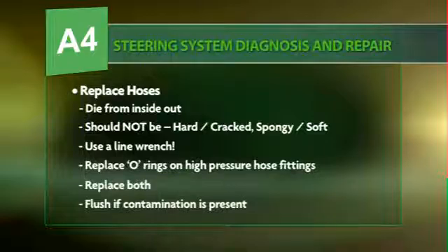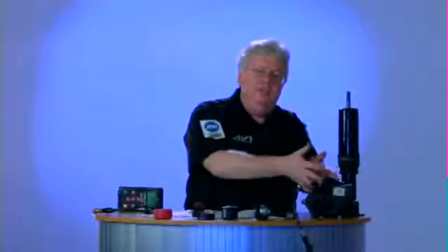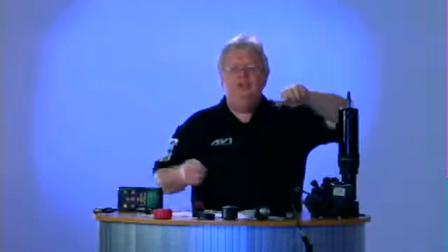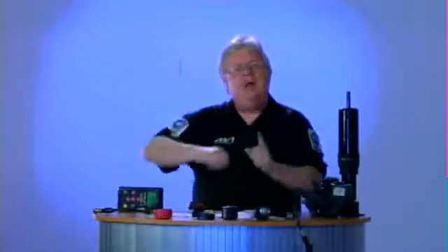So you want to take the return line loose out of the pump, and you want to fill the system as the engine runs, and you turn the steering wheel from lock to lock, but don't hang out, don't prolong the lock where you're hearing the pump groaning and laboring. Just do it for a second and then back off of it and keep turning the wheel.